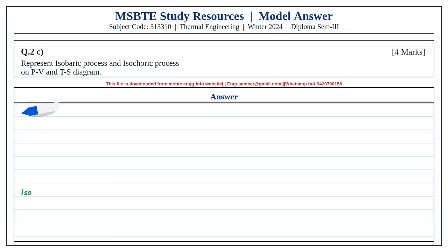Question 4a. Define various modes of heat transfer with suitable example. The three modes of heat transfer are conduction, convection and radiation. Conduction is transfer of heat through a solid body or stationary molecules without actual movement of matter, for example heating of a metal rod.